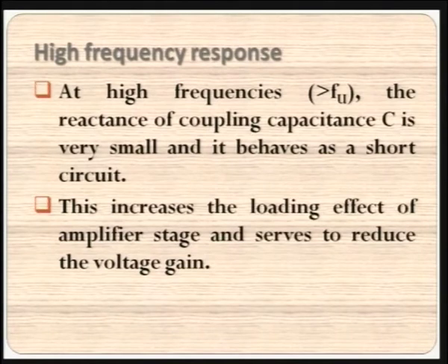At high frequency, the reactance of the coupling capacitor C is very small and it behaves as a short circuit. This increases the loading effect of the amplifier stage and serves to reduce the voltage gain. For the response we have for the high frequency range, again the coupling capacitor is the reason, and here the reactance is different, and it is again reducing the gain when the frequency keeps increasing.